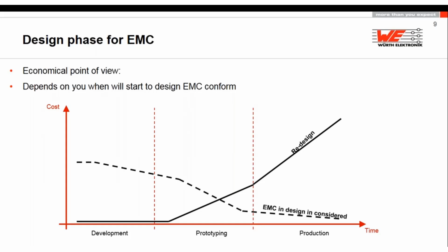Actually, EMC starts quite early. If you make a place for a 0-ohm resistor at VCC on every IC and you leave a pad free for a capacitor, then when you go to the EMC lab, you can just desolder the 0-ohm resistor and try a chip bead ferrite. If you had prepared a pad for a capacitor, you can just solder a capacitor.